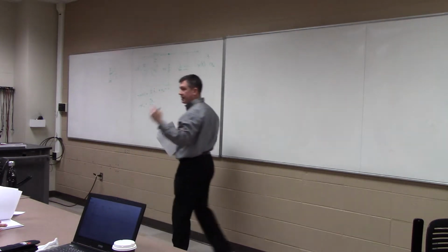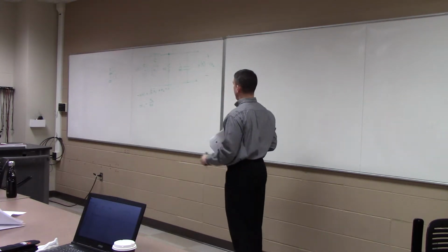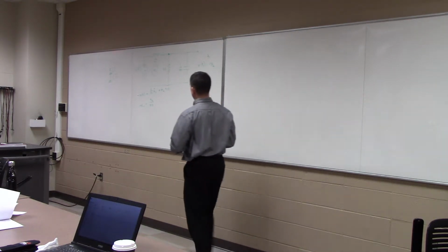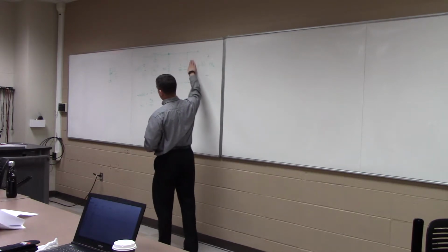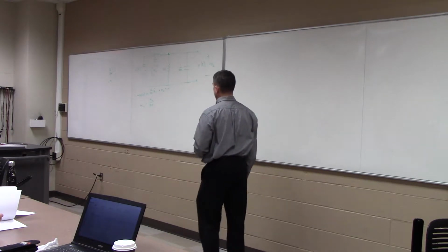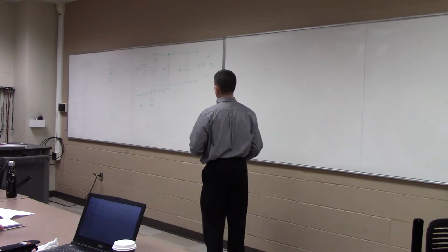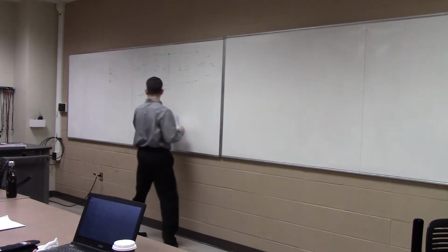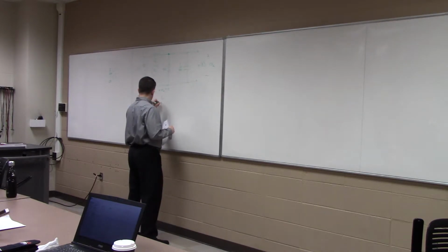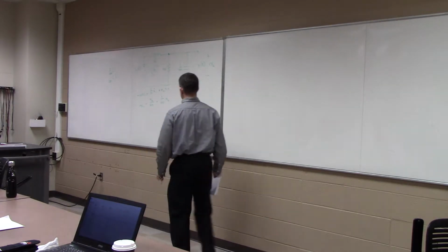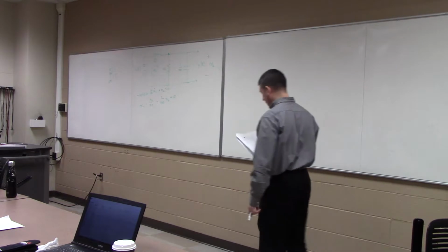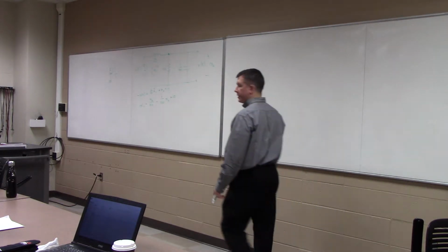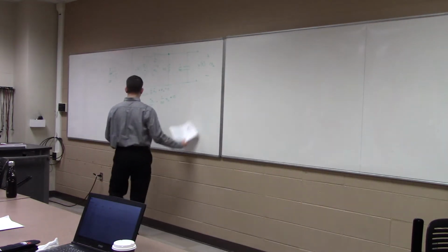That's going to be negative because I want the current going into the node. And the last one is the current going across this capacitor. I is equal to C dV/dt. So I'm looking for negative C dV/dt. That's equal to 0. And then the last one is just my output equation. My output y is just equal to x2.